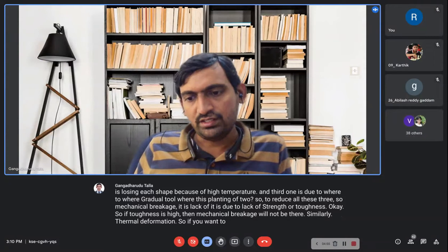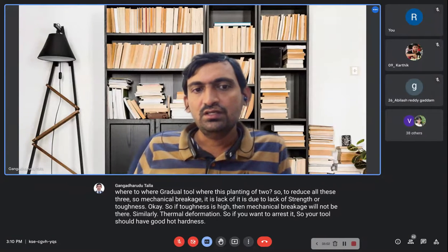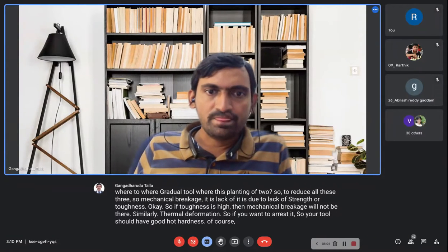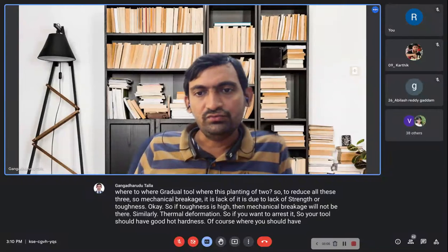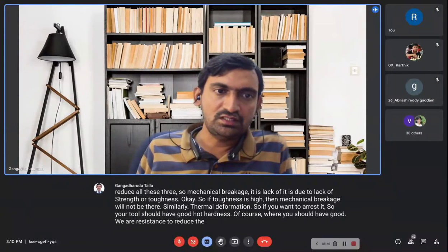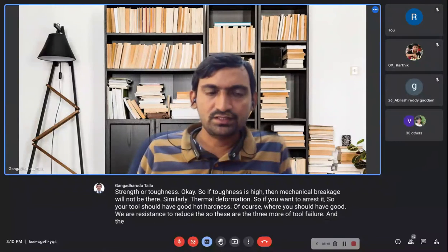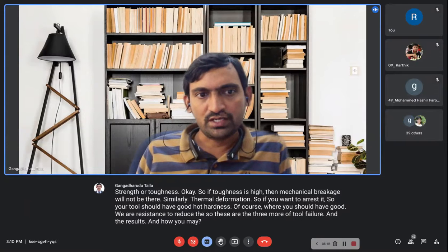If you want to arrest it, your tool should have good hot hardness. Of course, for wear, you should have good wear resistance to reduce the wear. So these are the three modes of tool failure and the reasons, and how you may overcome those kinds of failures.